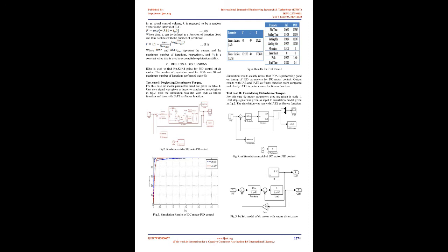Q is the volumetric flow rate into and out of the control volume. C_eq signifies the concentration at a balanced state in which there is no consideration of generation inside the control volume, and G is the mass generation rate inside the control volume. Wherein t0 and C0 are the initial values of start time and concentration, which depend on the integration interval.